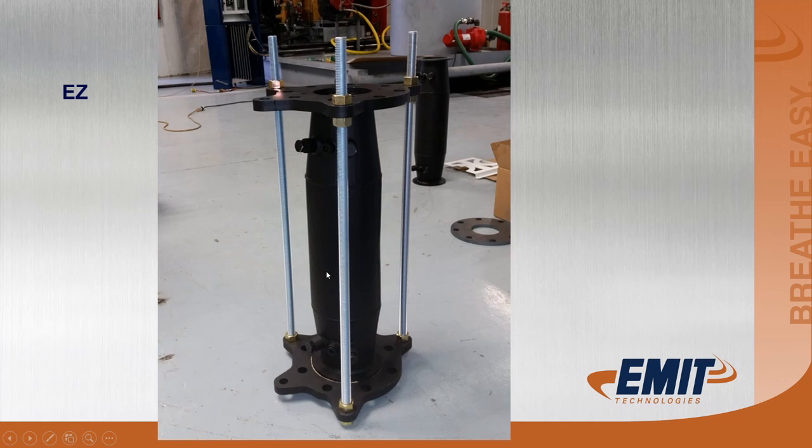EZ housing, this is a replacement housing for small horsepower naturally aspirated engines that don't carry a heavy load. You can mount this right down by the exhaust manifold and get as much heat utilization as you possibly can from the engine. Typically only applicable in low horsepower situations. Low heat is the main thing. You're going to utilize the heat coming off the engine as close as possible.